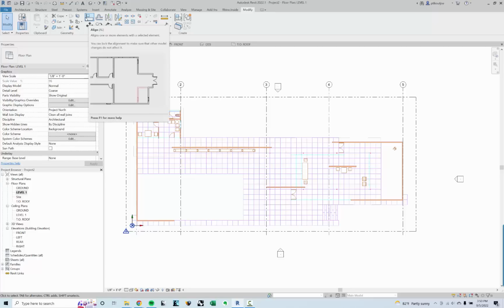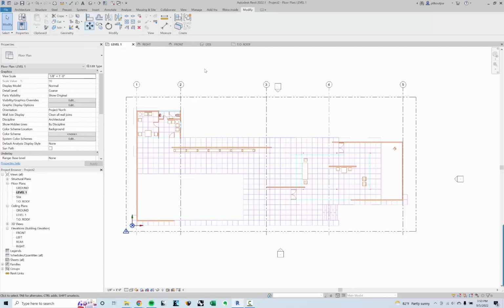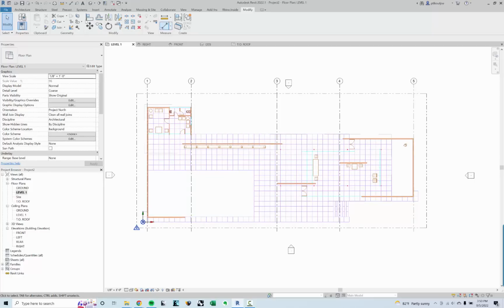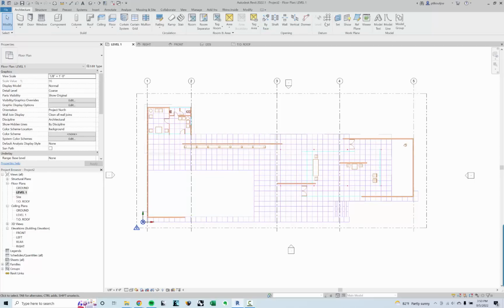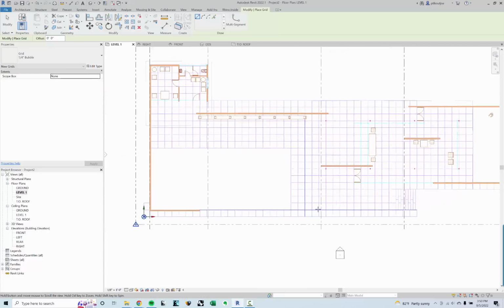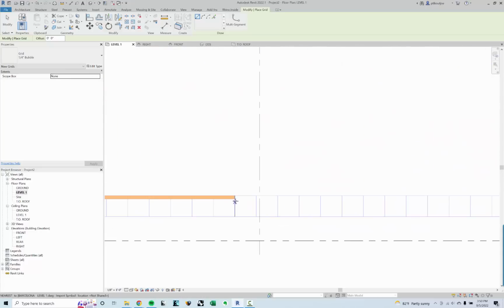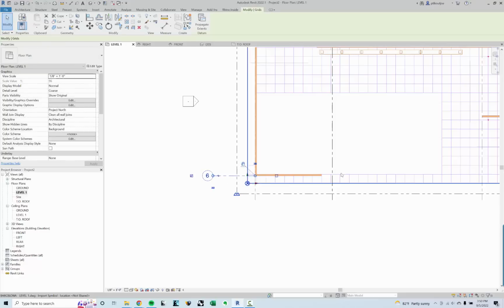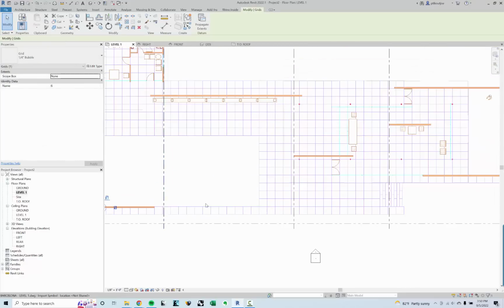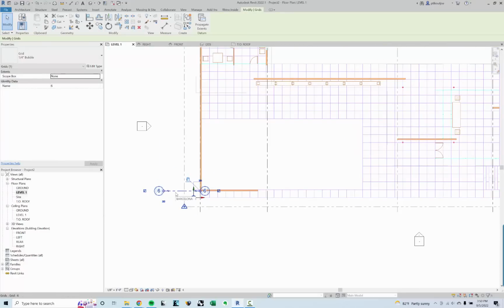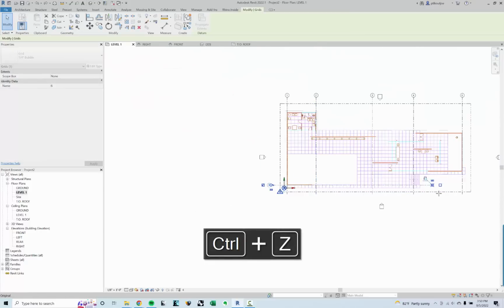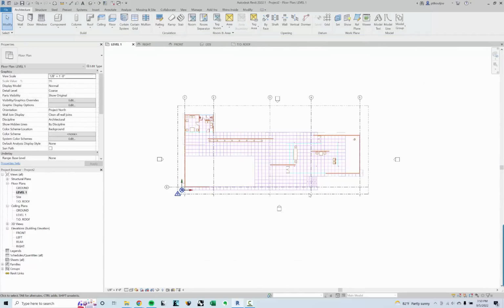And then you see there's like a little video that pops up that shows you how to use it. All right, so what I'll do is I'll put them the other way now. So I'm going to go back to architecture, grids. Let's have one here, and I'll just draw it this way. I want it to, oops, I want it to come down to here.